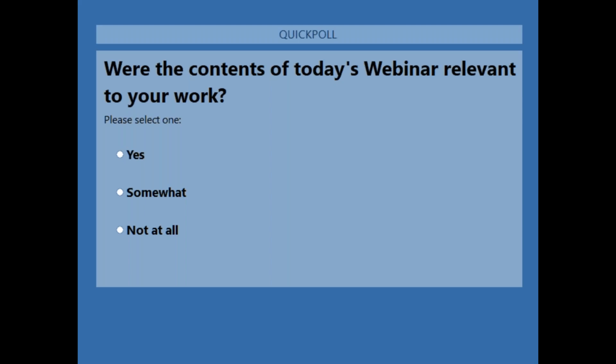I do not know what this question means, but it asks whether we can create a central file in AutoCAD Plant 3D. A central file is a concept we use in Revit, where the other stakeholders who form part of the Revit project integrate their piece of information into the central model file. Plant 3D works slightly differently. It works in a project format, and in the project you could have unlimited zones, which could be divided among different people. Ultimately it works on the same common project, so it's not a central file, but the same project.